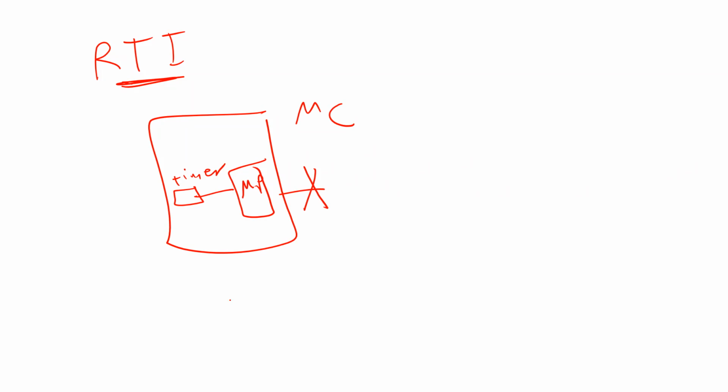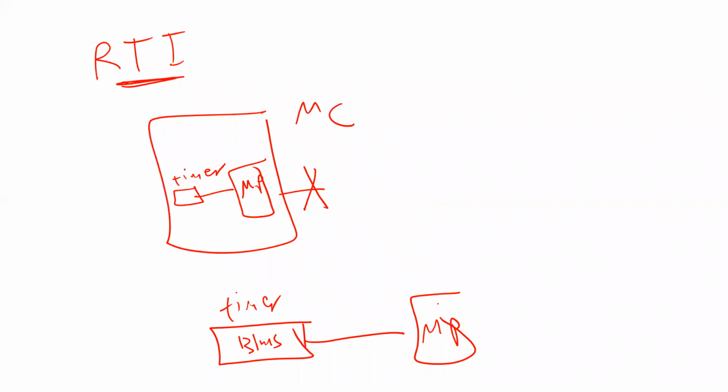Once you set the timer, you can ask the timer, please interrupt every 131 milliseconds. This timer is connected to the microprocessor, internally inside the microcontroller. This timer is going to trigger an interrupt. It's going to generate a pulse every 131 milliseconds, so that you can trigger an interrupt from the microcontroller every 131 milliseconds. This is for programming, and this is the most important thing.